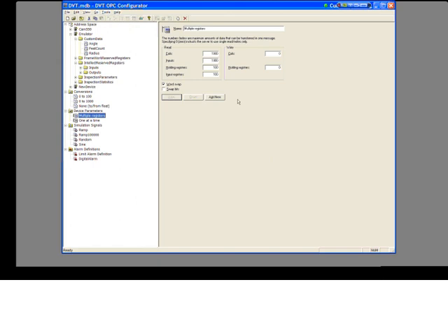You can also specify multiple registers. This is also predefined, and this specifies the maximum number of data that can be transferred for a particular data type: coils, inputs, holding registers, etc. You can change that. Eduardo, would that be similar to a block transfer then? Yes, these are block transfers.